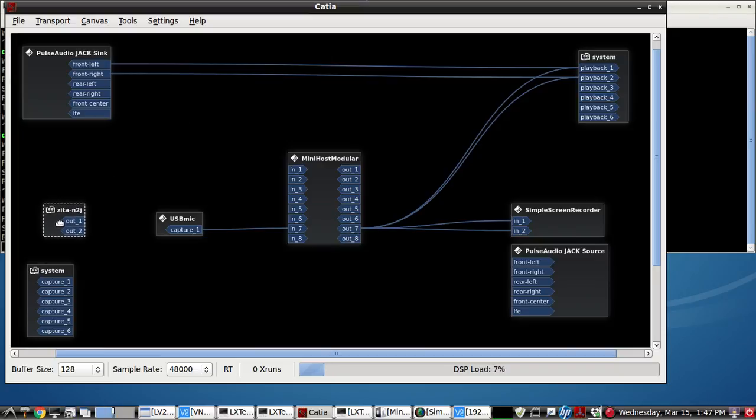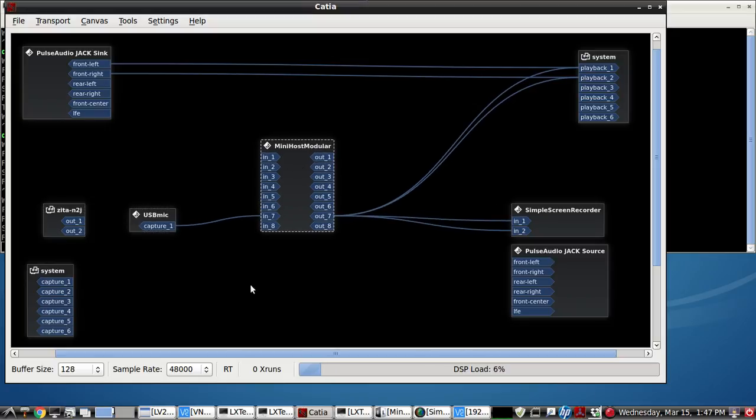The reason we want to send audio from here to the Pi is I'm going to send a CW tone over to the Pi. It's going to receive that tone and send it out its analog sound card to that audio-derived CW key switch, which then keys the rig. I'll get that set up here in just a second.